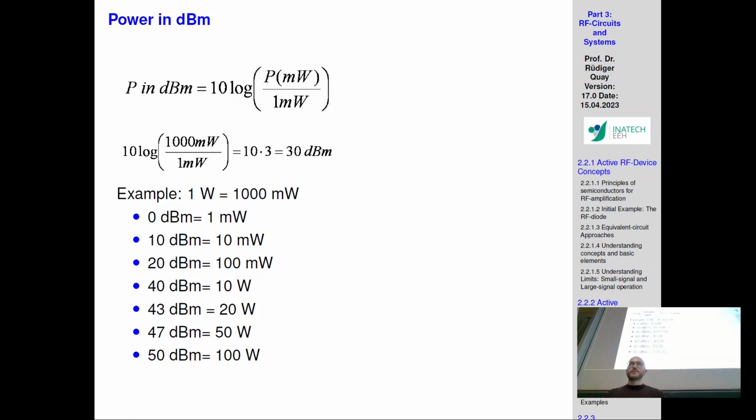In CMOS, for example, CMOS is also nowadays used for high frequency. It's not that only silicon carbide or whatever. Even standard CMOS is used for RF and high power as well. And what they do is that they have a ridiculous amount of transistors that are just daisy chained in series to each other, in order to achieve the required output power at the frequency point. So it's a very large amount of transistors that are either parallelized and then in series to each other. And this principle is followed also here. And you're doing it in chunks.